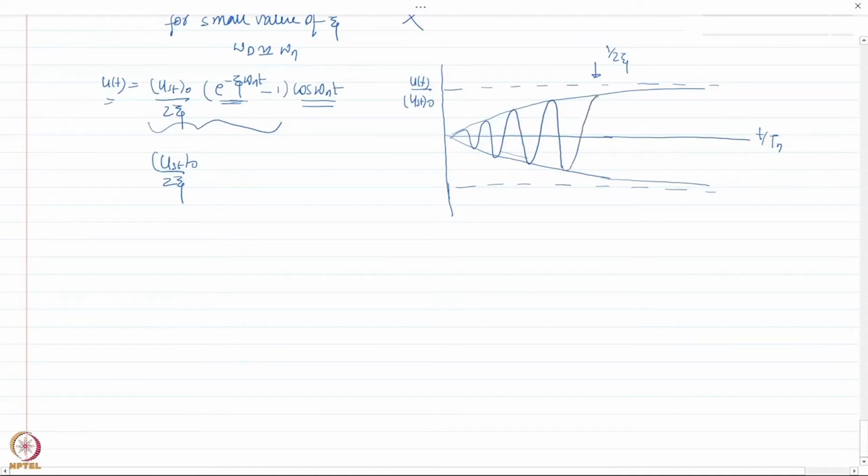However, because the system has some damping, what will happen after some time? This term here would vanish, and due to the applied force I would have a vibration with constant amplitude. So the response does not become unbounded if a system has damping.